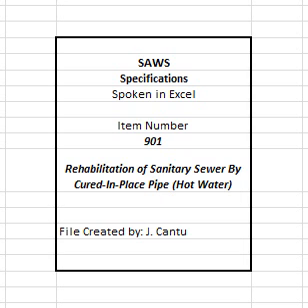E. The manufacturer shall provide the minimum pressure required to hold the tube tight against the existing conduit, and the maximum allowable pressure so the tube is not damaged. These pressure ranges shall be maintained until the inversion has been completed. A temporary water meter shall be installed on the fire hydrant, if used for inversion process. The cost to coordinate and install the meter for construction purposes shall be at the contractor's expense.